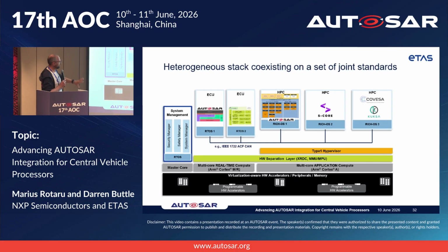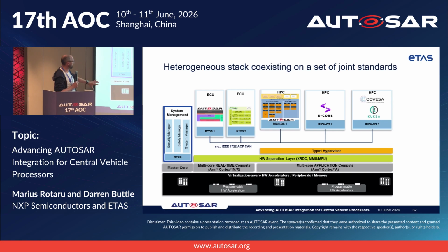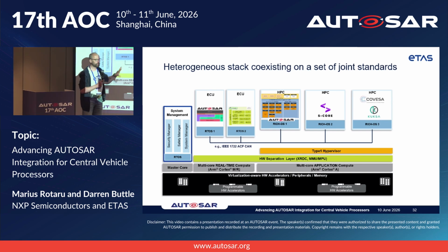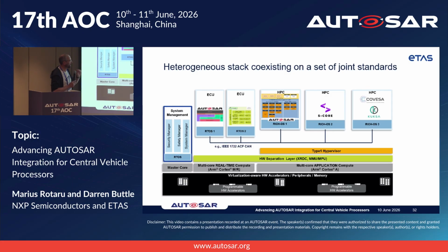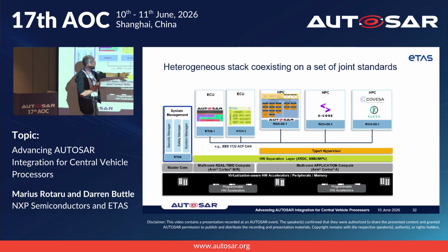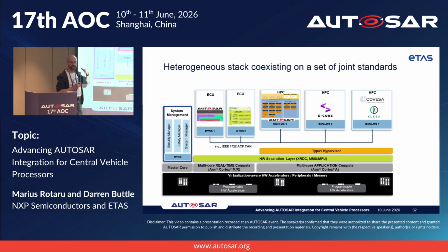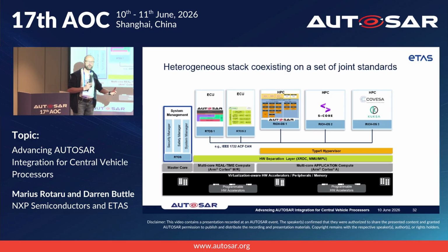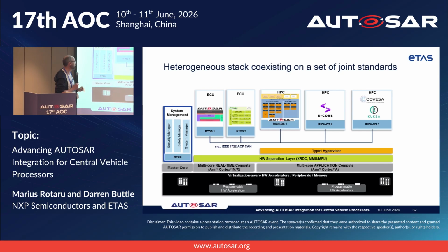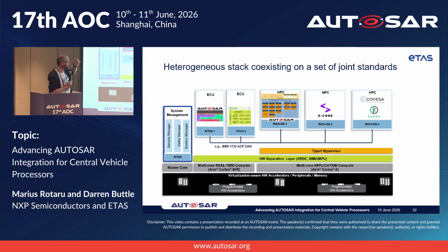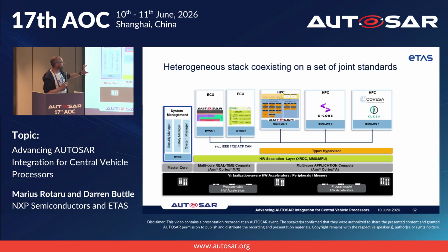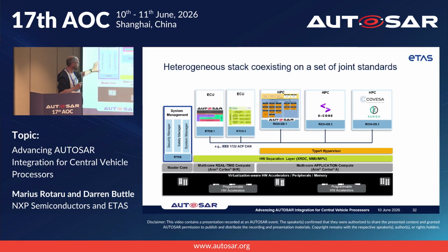So what we actually have, and this is again reflecting what Marius has said, is this idea of being able to put multiple different things on multiple different cores. For example, the demonstrator that we've got running out there uses all the Ethernet virtualization technology to allow all of those individual ECU partitions to communicate without changing anything necessarily in the software, to allow them to talk on the virtualized hardware. We've also got the system management that Marius mentioned over here. This is the functional foundation subsystem.